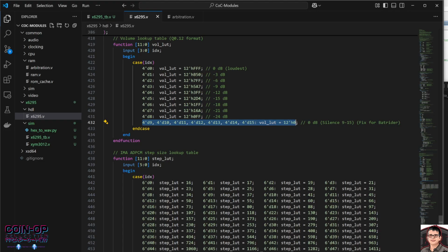So when you're processing audio, each sample is 4 bits, right? We saw that in the data sheet. Each 4-bit sample describes a delta from the previous sample's position, right? So all the samples start at 0. So your waveform starts at 0, right? And as you step through, you're retrieving the ROM, you're decoding it, and you're applying the step LUT and all that stuff.